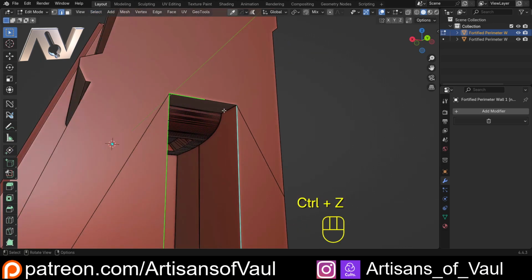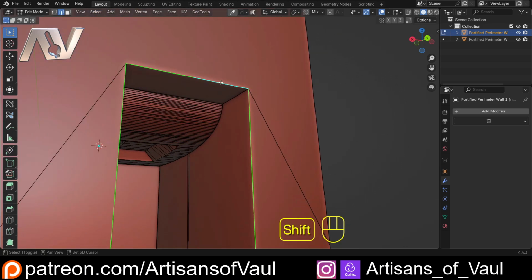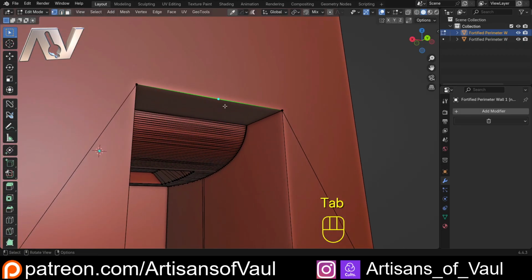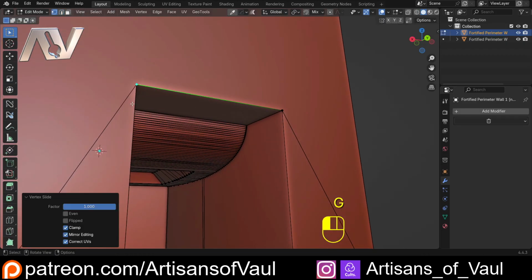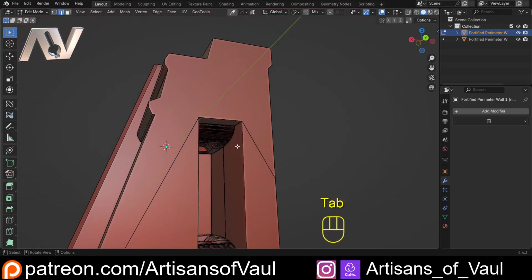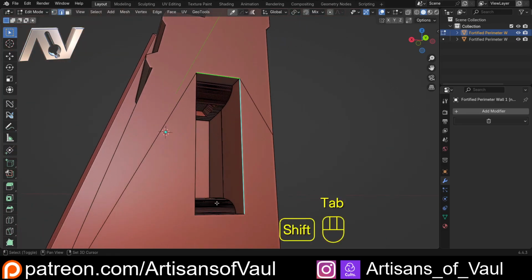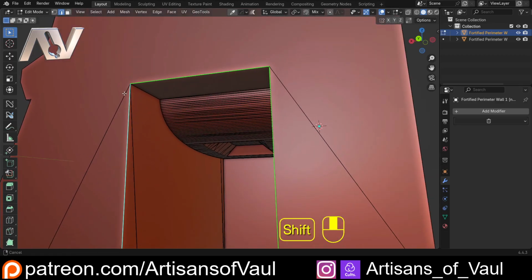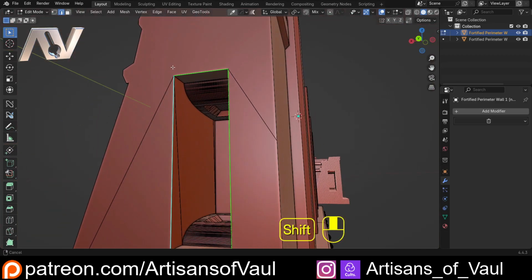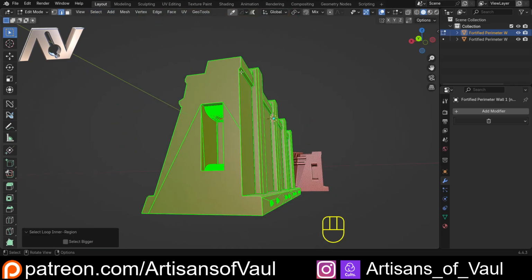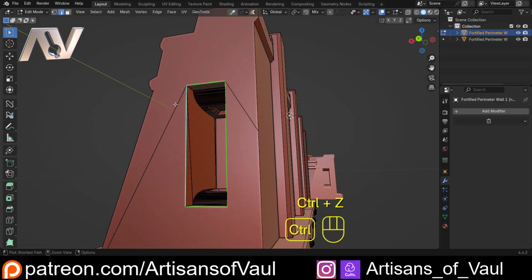So if you find that happening, basically there's a gap, even if it's tiny, in your mesh. A lot of the time this can be vertices that are on top of each other. If I just move that all the way over here, sometimes you can't even see this. So we're going to go into Edge mode, select there, and there, and sometimes Blender will not recognize that these vertices are on top of each other, and if I go to select loops and select in a region, it selects everything because it doesn't recognize this as a loop.